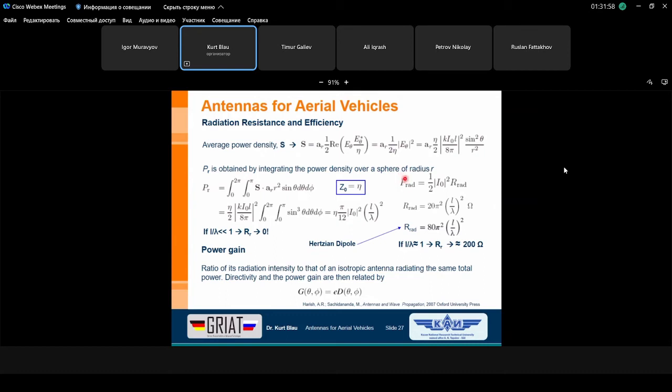The radiated power we can express as a half times the current at the origin squared times R, nothing else than Ohm's law, and this is what we want to know: our radiation resistance. The half comes because we have to use the average for power, and for the current we have to insert the maximum value.